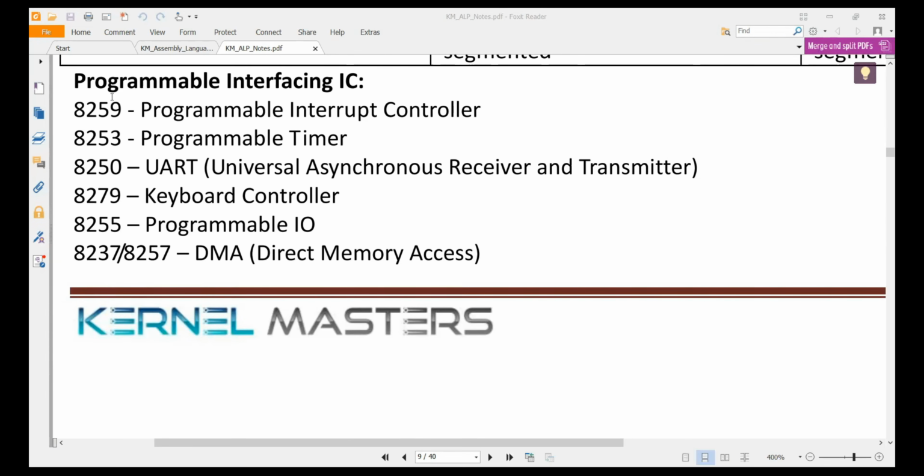Whatever the controller, the concept is the same. The ARM processor also has one, but on ARM it is called the GIC, the General Interrupt Controller. The name is different, but the purpose is the same, the same non-vector interrupt concept and methodology. The GIC handles 128 interrupts.